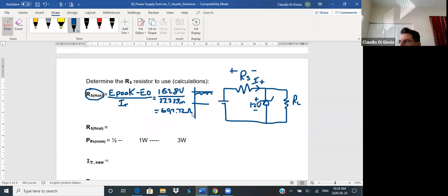Now if I were to put this resistance in the circuit, I would get the current I need here, which was 15 milliamp, and I get the IZ min of 8.33. Do you understand that if I choose one in my kit that is larger than this, then my current IT will be lower?